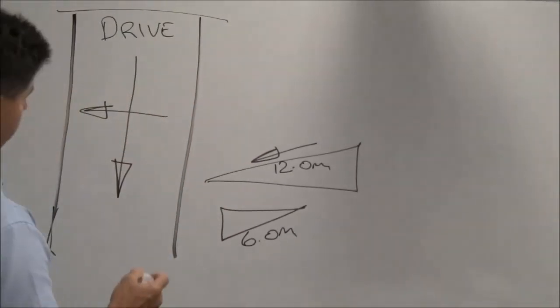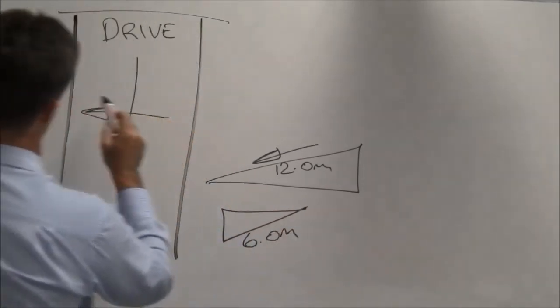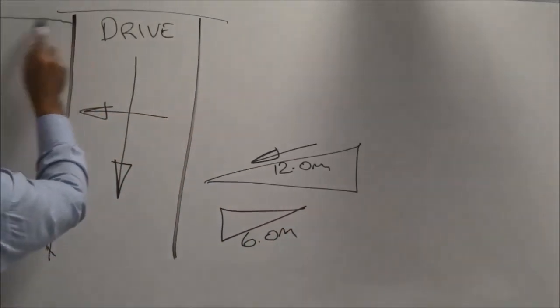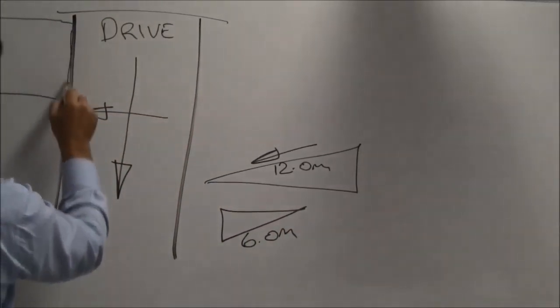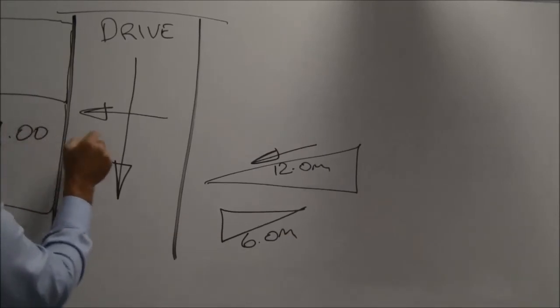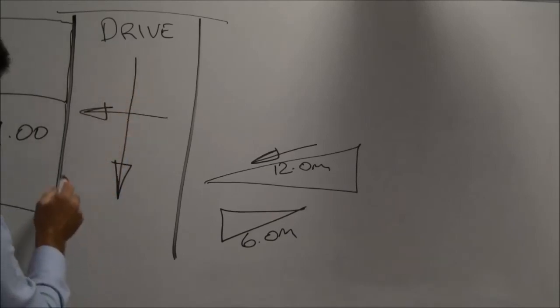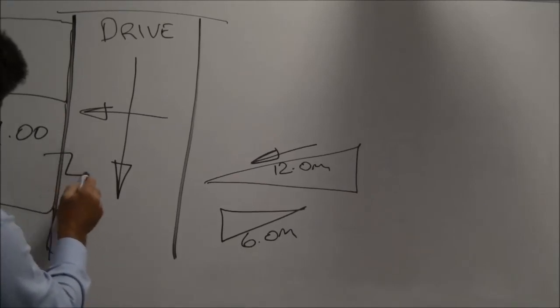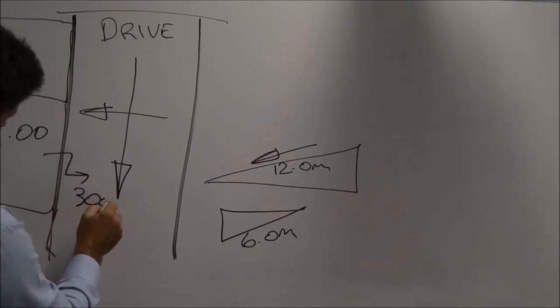Okay, so if I'm coming through my driveway here and I've got my house garage sitting in here and my floor level off my house is sitting here, generally if I've got an RL in here of 9, I don't want my water level inside this driveway to be above my floor level inside my house. So I'd give myself a freeboard here of 300 mil.